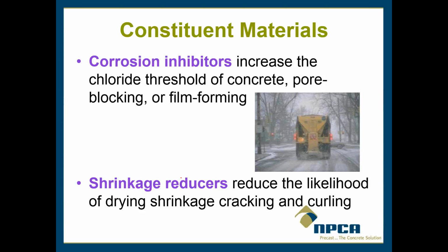Okay. Shrinkage reducers. Sometimes you'll see these spider-like cracks in the unformed surfaces of your product. Those are typically called plastic shrinkage cracks. So the water in the concrete is evaporating at a rate faster than the hydration reaction is occurring. The evaporation of the water is causing tensile stresses within the concrete, and that causes it to crack. So shrinkage reducers can help with the drying shrinkage.